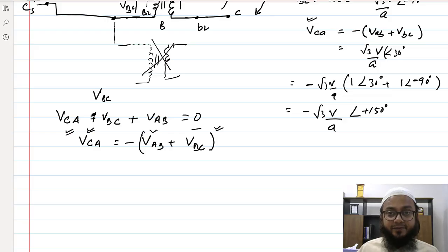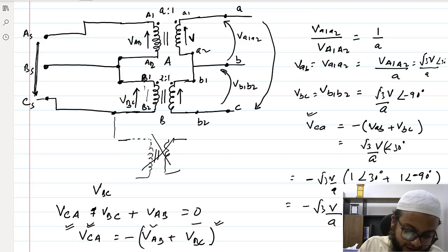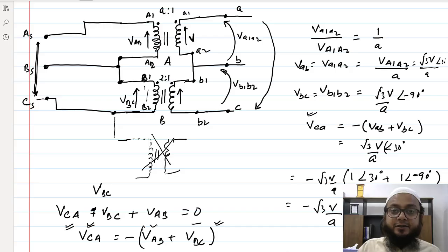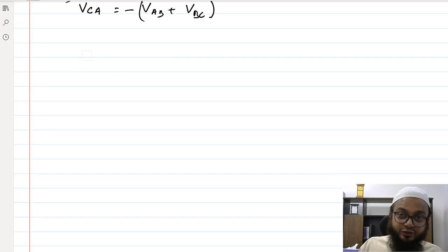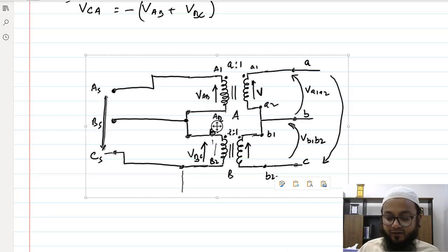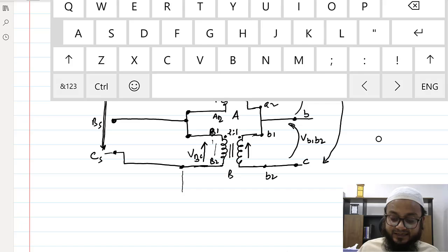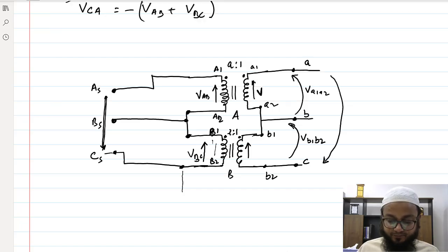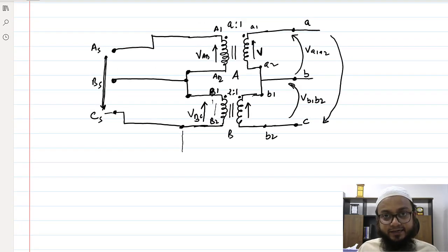What would be the power handling capacity? So let's say this connection, I'm using it to power a load. The logic says if you have 3 transformers, the power handling or the apparent power of that transformer entire rating was 3 VA or 3S, let's say. If each individual transformer's rating is S, for 3 transformers it should be 3S, right? But we'll see whether this is actually happening or not. Actually the power gets reduced.